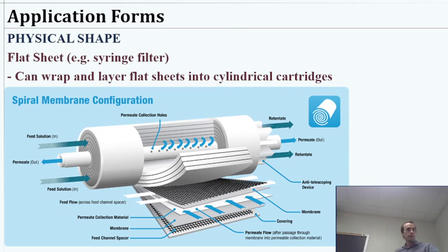Okay, so physically, what do our membranes look like when we create them? Well, if you think about a flat sheet membrane we talked about, you could just take a piece of paper or a sheet of membrane and just clamp it down in a system where you can pressurize. You can apply water, maybe into a tube here, into this little pressure chamber, and then force the water through, and then collect it on the other side, right? That would be the simplest way. It'd be a lot like our granular filtration beds.